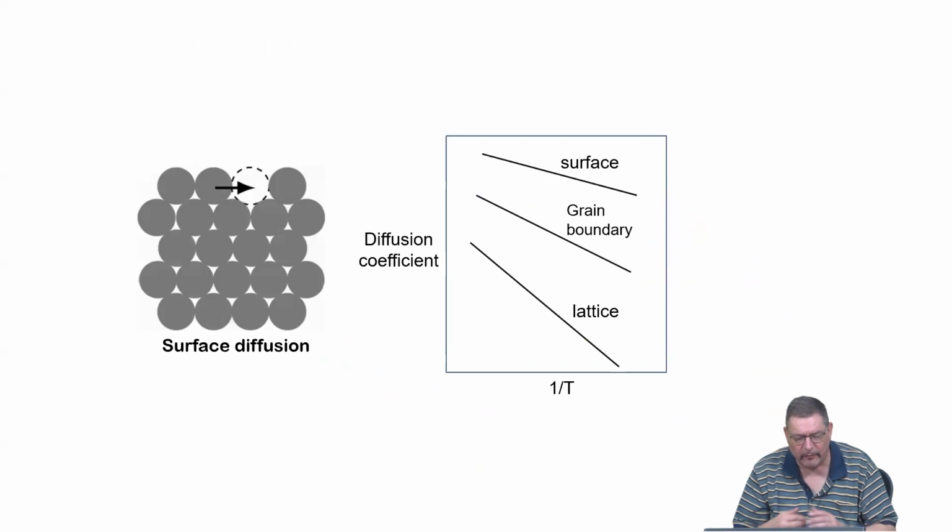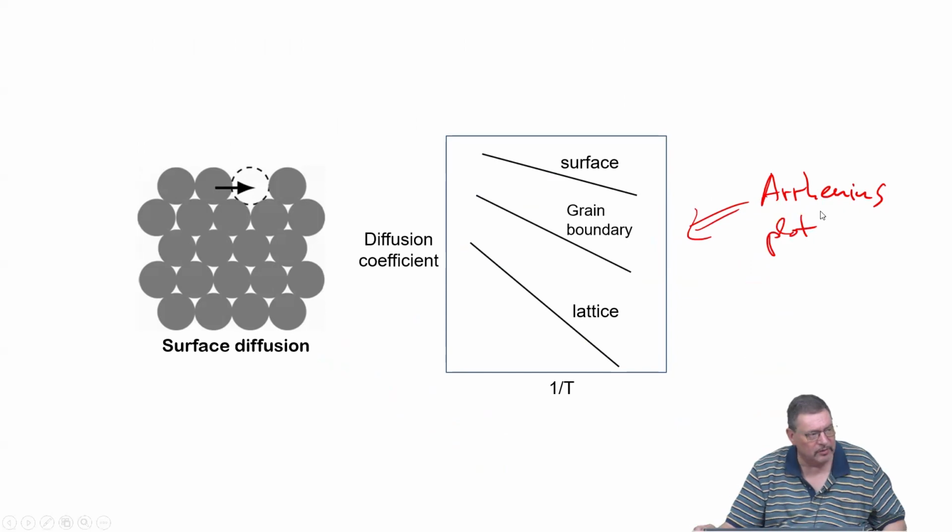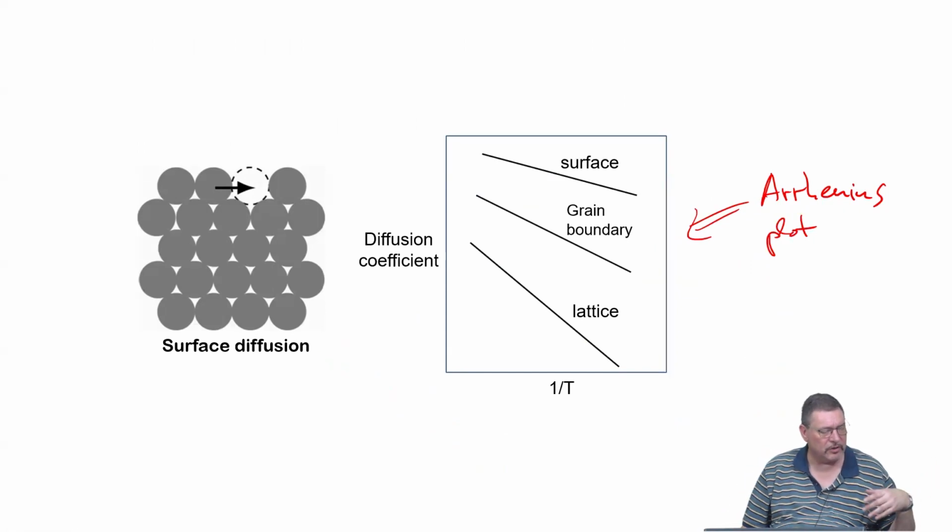And if we compare now substitutional diffusion and surface diffusion, I already explained, there is no atom on the top, so it's very easy for the atoms to diffuse. Then we have in this Arrhenius representation, meaning you plot the diffusion coefficient as a function of 1 over the absolute temperature, from the slope of these lines you get the activation enthalpy.